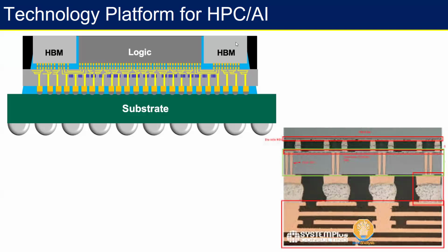So the point is that in HBM, you see that there is this connection between these two that is needed. So to make the connection, these wires have to go. Now, you could say, okay, why do I need bottom wires? Why can't these connect like this, just on the side? So the point is, when you are putting that, you do need a substrate, right? You cannot put this logic die in air. So what you are starting with is always a board, right?